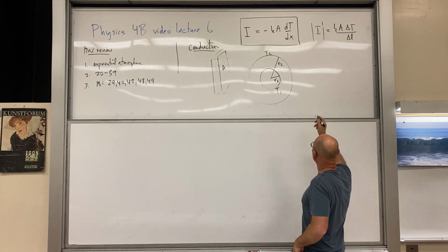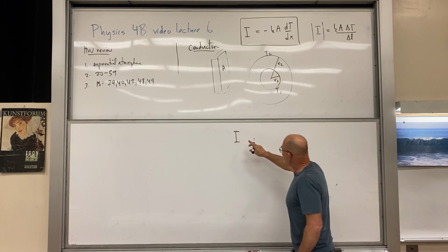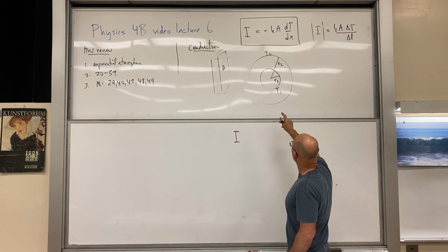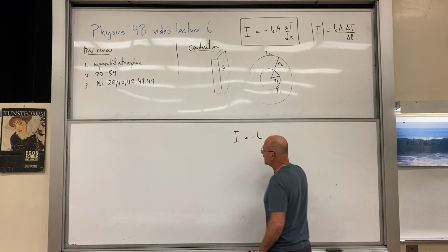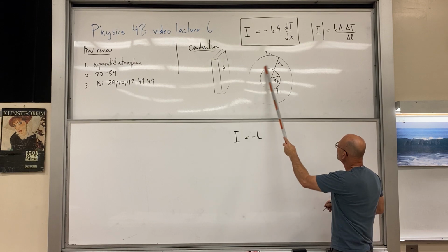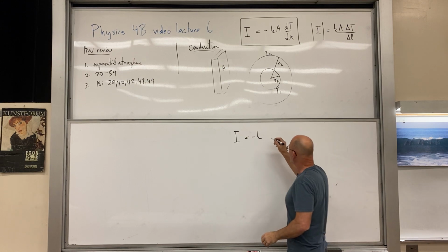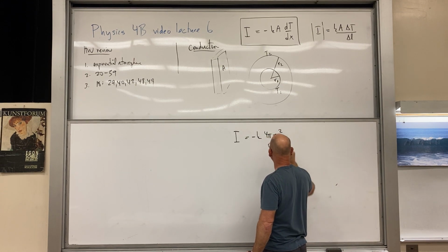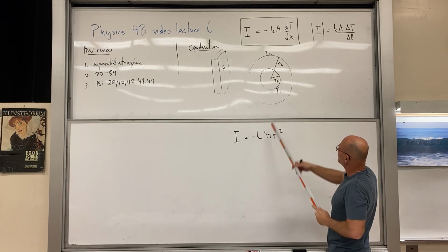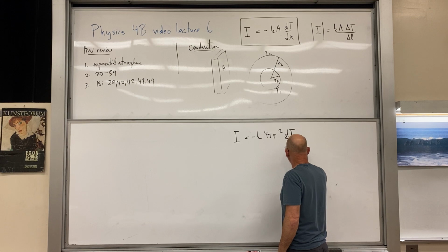And so to account for that, we're thinking of this as a constant in the problem. That's the constant energy flux. And what we have now is minus k, but a shell here has the area, since it's very thin, we think of it as a slab, but it's wrapped around as a sphere. We have 4 pi radius squared. Wherever we are, r between r sub 1 and r sub 2, that's k 4 pi radius squared, and then the gradient in the temperature is with respect to the radius.